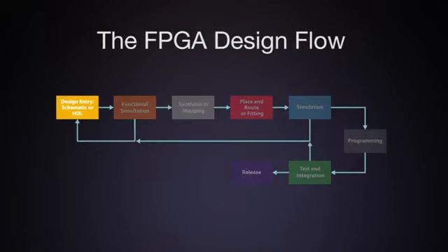The design begins with the design entry, continues with simulation to verify the logic is implemented as expected, and then the tool will perform synthesis, also called mapping, to map the logic to the device architecture. Next, the tool will create the interconnection between cells by placing and routing, or fitting, of the design. Timing analysis using static timing tools is then required to assure there are no setup or hold violations in the design. Running another simulation after fitting is done is a good practice and it can uncover timing issues.